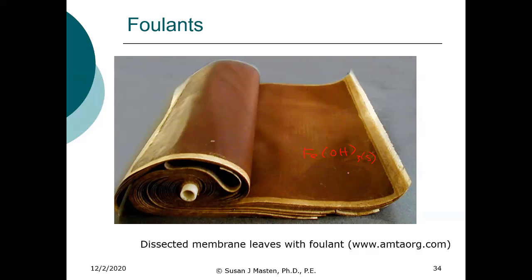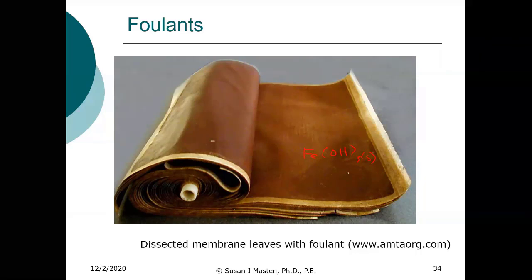And you can probably imagine getting flow through that membrane is extremely difficult. About 20 years ago, membrane filters were put in Chelsea. They didn't put in an iron treatment system, and within a few weeks, the membranes all looked like this. They then had to go back in and retrofit the plant in order to remove iron prior to filtration, to prevent this.